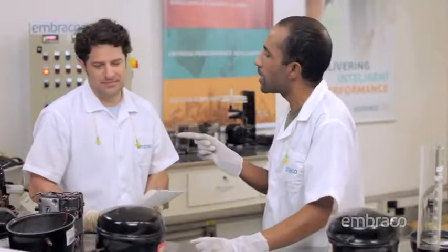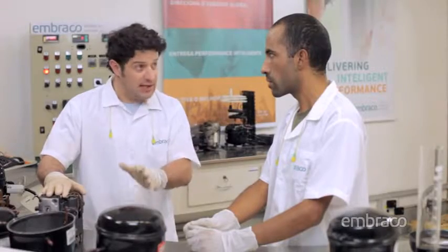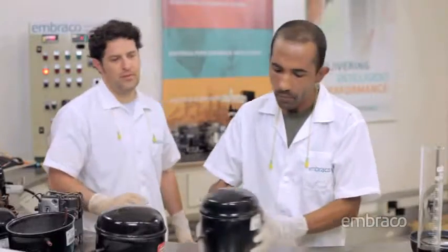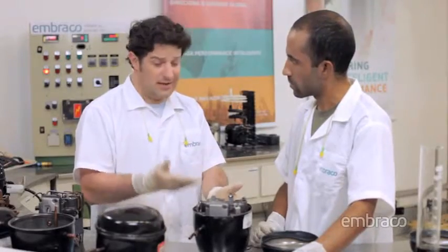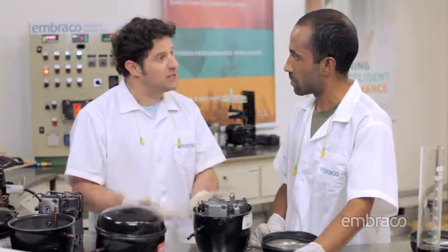Yes! Taking advantage of this opportunity, Peter, if the compressor suffers some impact but doesn't show any apparent damage, does it still work? Mark, although the housing is made of steel, the compressor should be treated with care, since the impact can cause severe damage to internal components, even if the housing isn't dented. But doesn't the compressor have springs to absorb impacts? Internally, the compressor has shock absorption springs and is tested to withstand normal shocks during shipment of the compressor or refrigerator. Now, excessive impact may damage the compressor's radial clearances, causing it to not work properly.